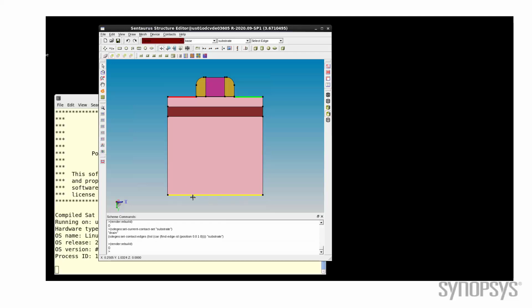For the simulation of 2D SOI MOSFETs, artificial body-tie contacts are sometimes useful. These contacts are placed typically at the interface between the silicon epi layer and the buried oxide, near the source side of the gate corner. Before such contact can be defined, 2 additional vertices must be introduced to create an edge.